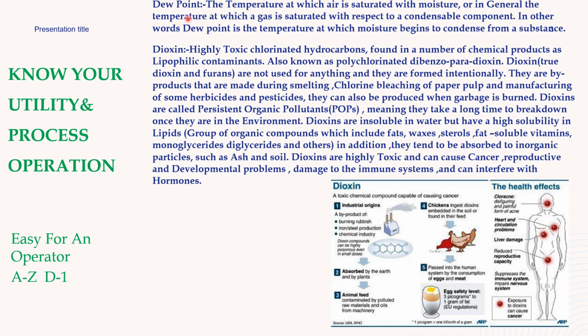Normally, dew point is important where instrument air is used. Instruments are used in all types of industries, and all instruments are pneumatically operated. So moisture must be removed from the air pressurized in the compressor, because if the air is used as such, it will condense at low temperature. So we have to reduce the dew point by means of an instrument air dryer. The dew point is reduced to minus 40 degrees centigrade minimum. It can go even lower.